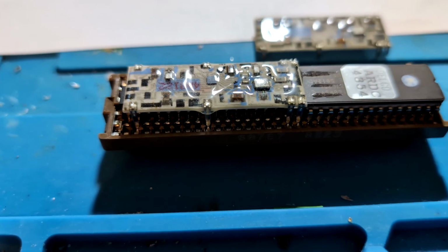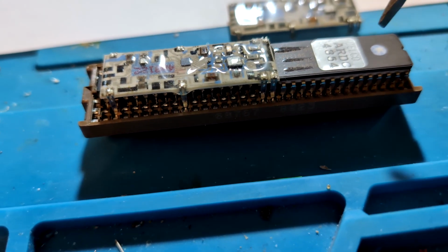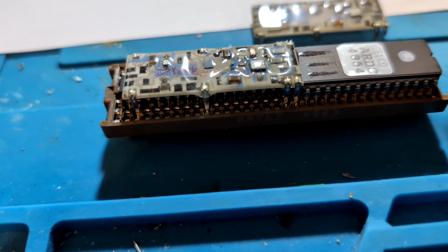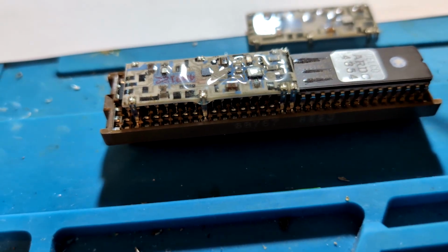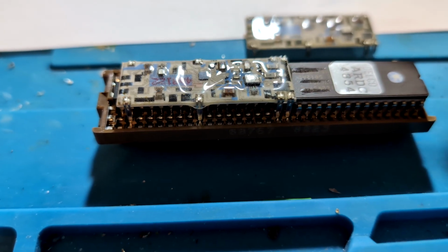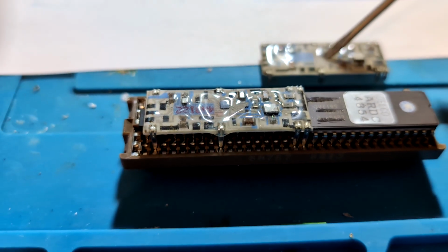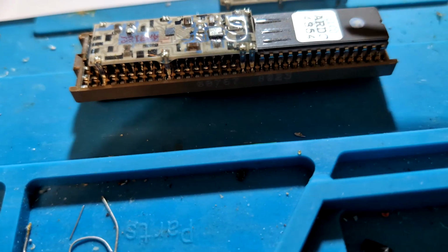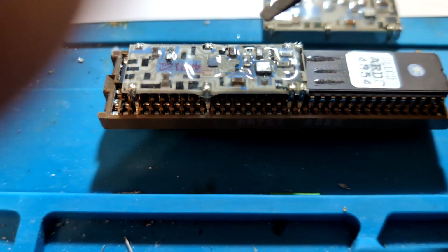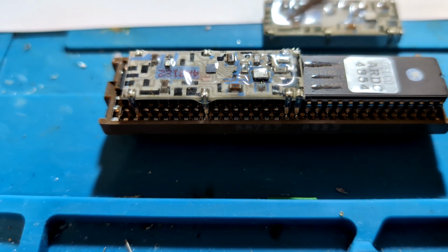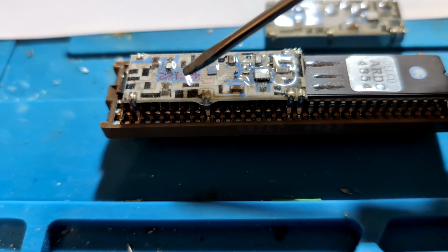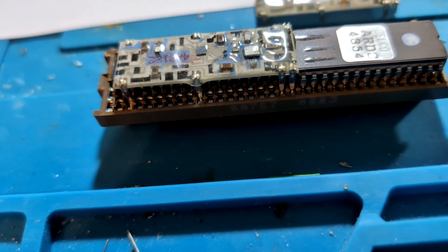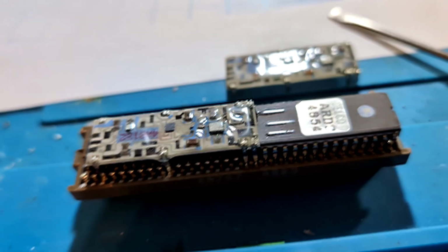TPI trucks had a very similar Memcal. The chip was different, but it did have this same knock filter. And supposedly, though I've never done it myself, you could desolder the knock filter from one of those and solder it onto your 1227730 Memcal, and you should then have a proper V8 knock filter. Again, that's theoretical. I've never actually done it.